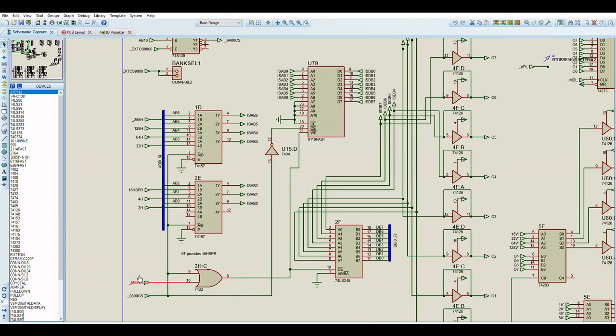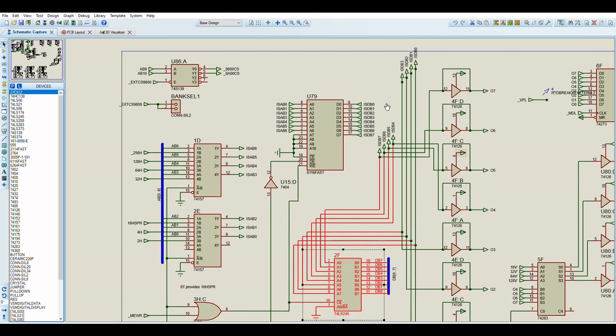But basically, if you are writing 9800 in hex, then it switches the data input from the data bus, the external data bus, through here, and then it starts writing data into these signals here, which eventually go into the internal Sprite data bus, ISDB, which can go to, say, for example, the internal Sprite registers here.